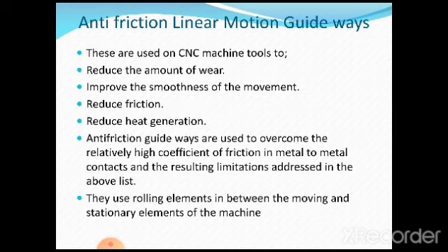This is one of the plus points here which we are going to see. There is a continuous movement. There is no cut of the movement here. Just we have shown here like this. So again you can have one more element like this, similar to this, and again you can proceed with the motion. Okay, so their main characteristic feature is that there is continuous roller circulation which allows unlimited linear movement.